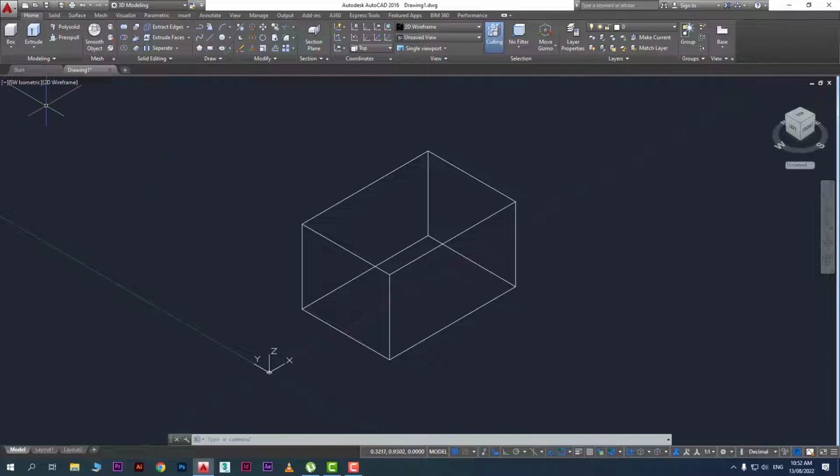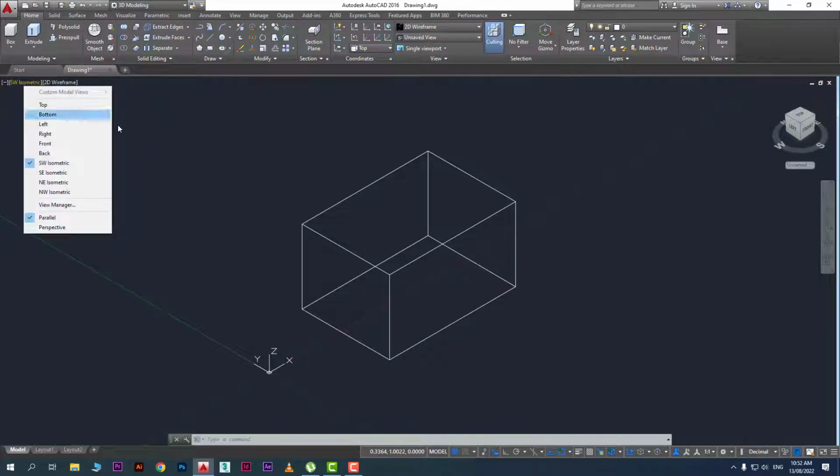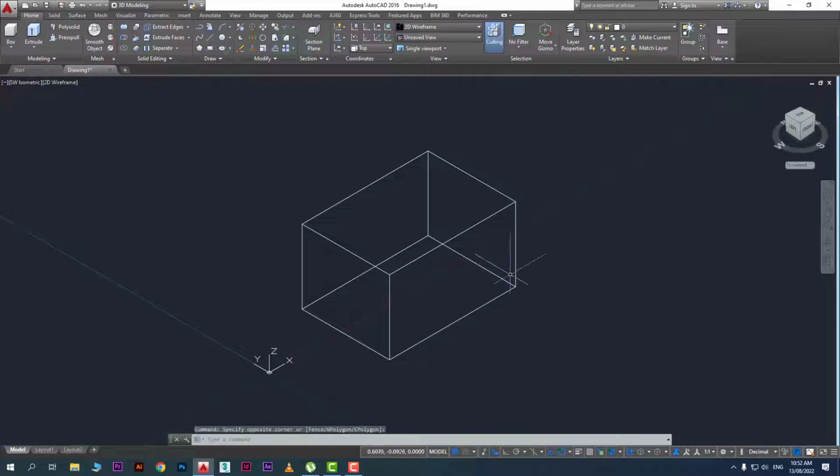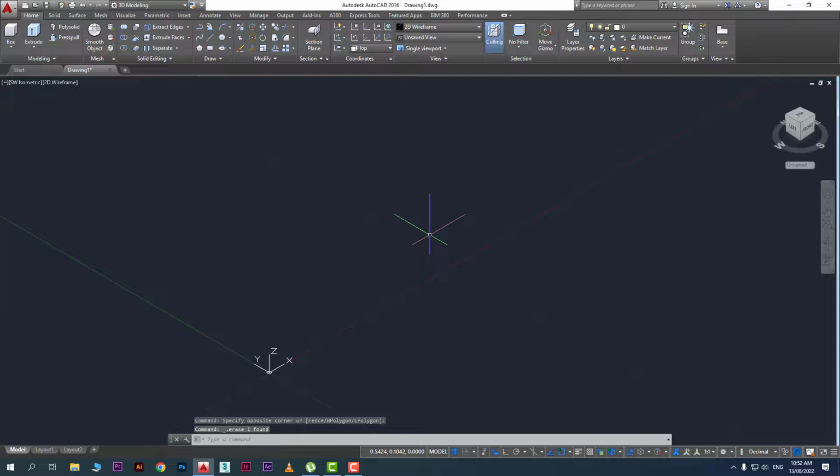Alright, so now I have changed only the space, the 3D space from here to Southwest, and I have just drawn one object. If you delete this object, we can also draw a line. If you take the Line command, it's simple, we have it here, or you can press L as well. So with the Line command, you can start from here like this.